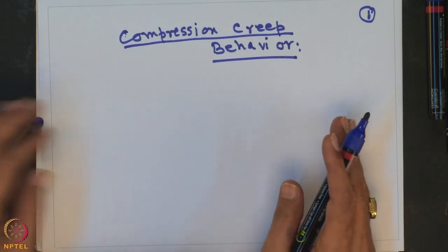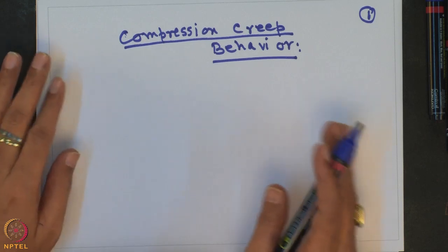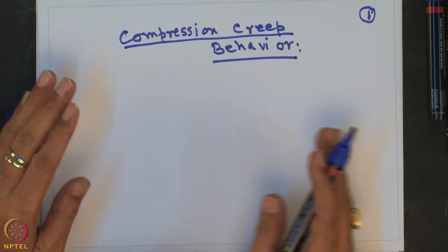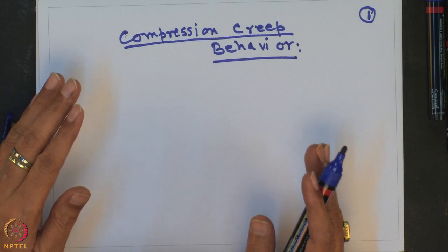But this test is very long term testing, and this is time temperature superposition, and it takes a long time to perform this kind of compression creep test of the EPS geofoam material. It may be 100, 1000, 2000, 5000, 1 lakh minutes.